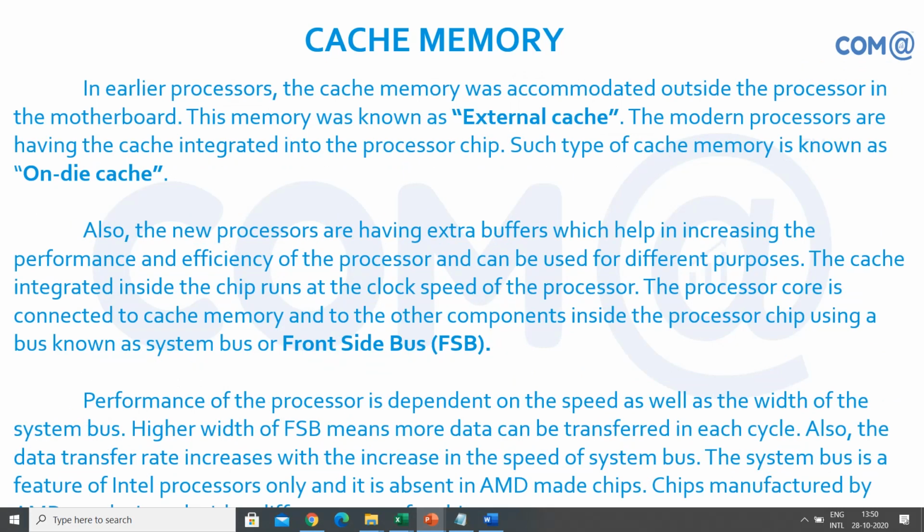In earlier processors, the cache memory was kept external, I mean, external to the processor on the motherboard. So the processor took some extra time for accessing the data from the cache memory. In later designs, they moved part of the cache memory inside the processor. Now the processor has faster access to the cache memory. It does not need to travel through the motherboard to find the cache memory. Since it is internal, all the information will be captured and it will have faster transactions. That is the difference between external cache and on-die cache, otherwise called internal cache.